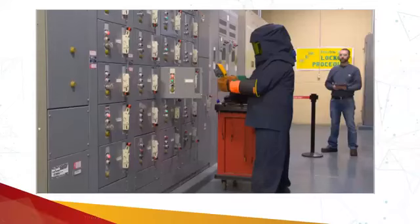So this person is performing some thermography. This could be the outermost boundary, and it could be an arc flash boundary or the limited approach boundary, whichever is greater. He's wearing the right amount of PPE, which seems to be for above 24 cals per centimeter square, or it could be 40 cals per centimeter square, and he's performing thermography on the low voltage side.